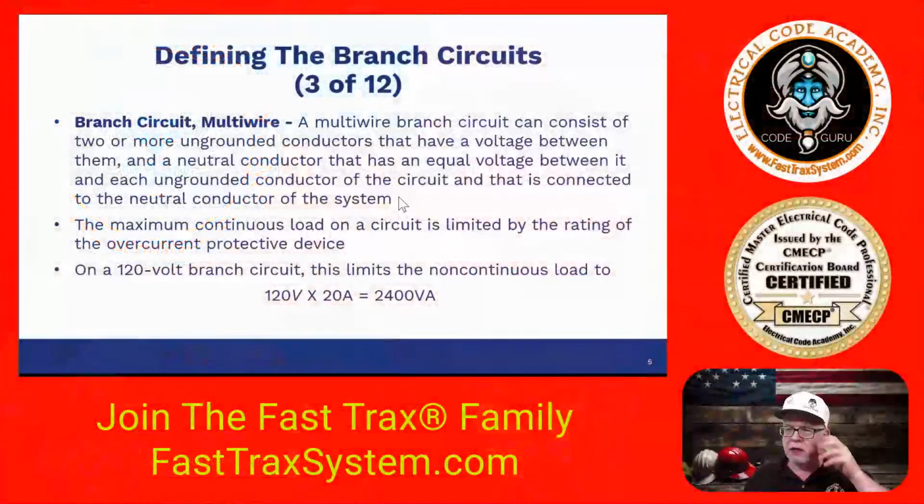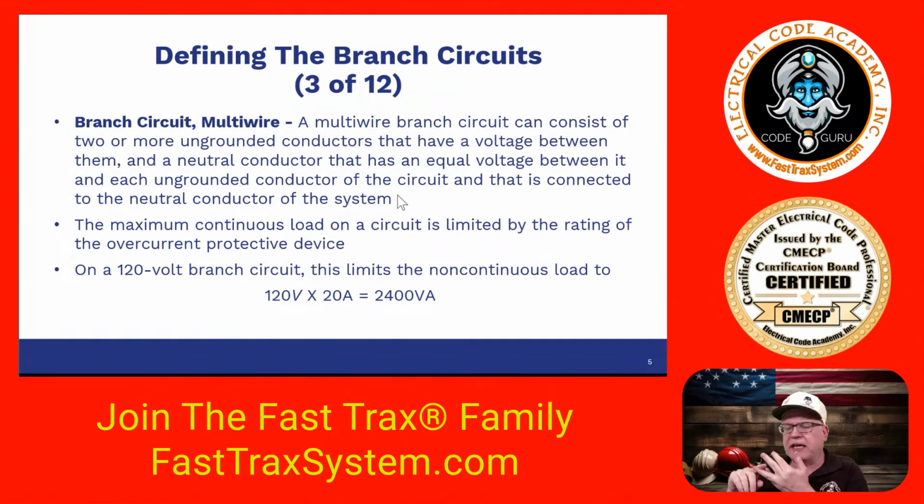All right. So you have appliance branch circuits, you have general purpose branch circuits, you have individual branch circuits, you have motor branch circuits, and of course you have a multi-wire branch circuit. Okay. Now, let's talk a little bit more about these branch circuits. The maximum continuous load on a circuit is limited by the rating of the overcurrent protective device.